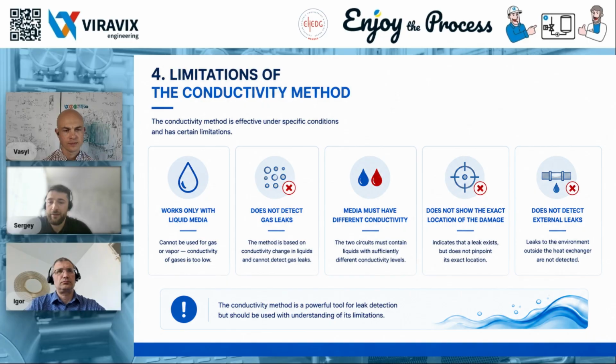It can confirm that there's a leak between the circuits, but it can't pinpoint where the leak is or detect an external leak. This method can actually be used while the heat exchanger is in operation. In fact, it's one of the methods that can be applied without shutting down the system.